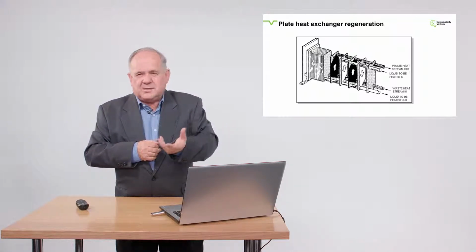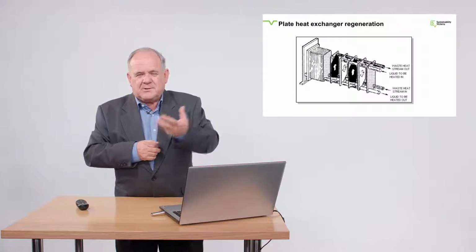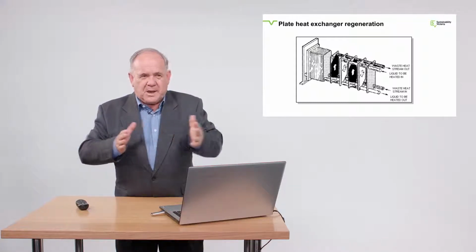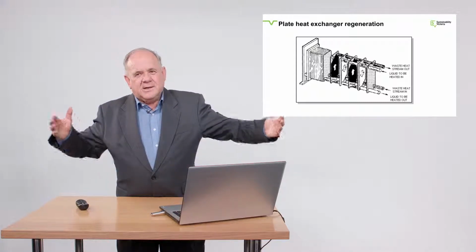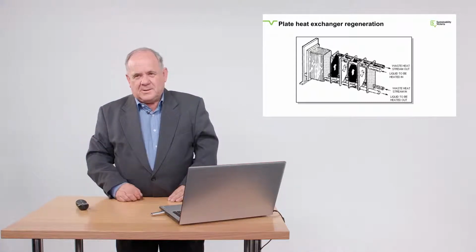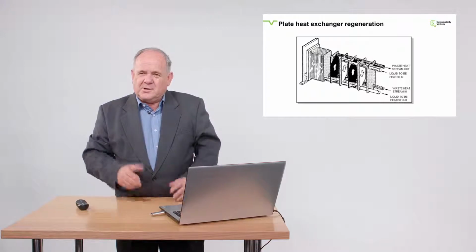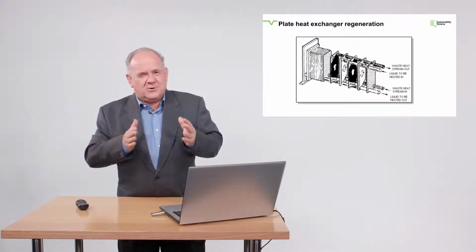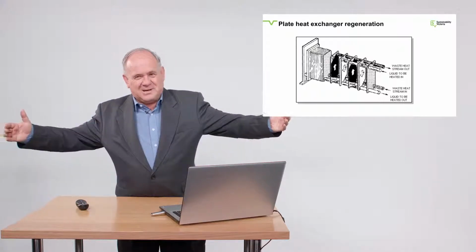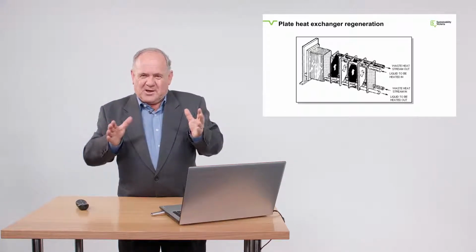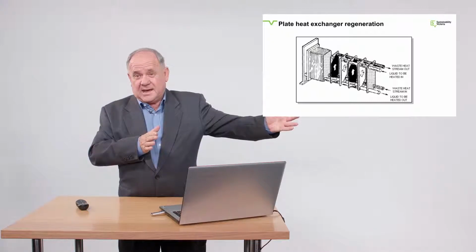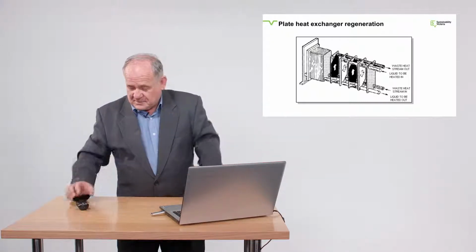Over the years, it used to be 70%, but now as energy prices go up, the amount of regeneration in the plate heat exchanger increases, because you can justify the extra capital. Unfortunately, it's not a straight line. The more and more energy you try and recover, the bigger and bigger the heat exchanger. So it's a cost justification of how far you go in recovering the heat against the gas and power prices.